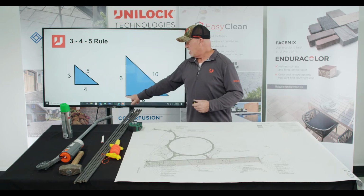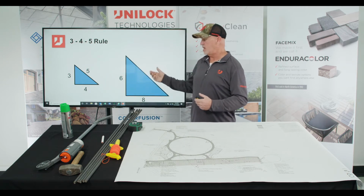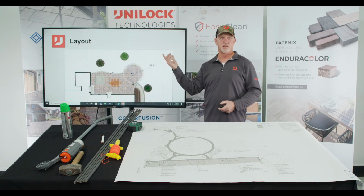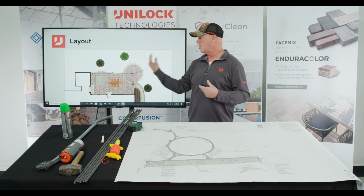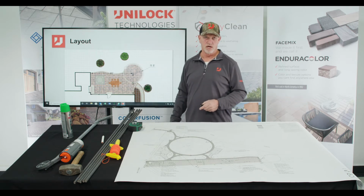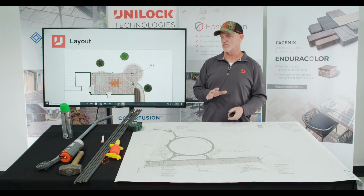So again, if I'm 3-4-5, potentially I want to do 6, 8, 10. On the installation that we're going to have on this plan, we're actually going to use a bigger number. We're going to try to maximize that 3-4-5 rule with a multiplier that will work for us to best achieve accuracy on this layout. So with that being said, a few tools that I want to bring with me outside.